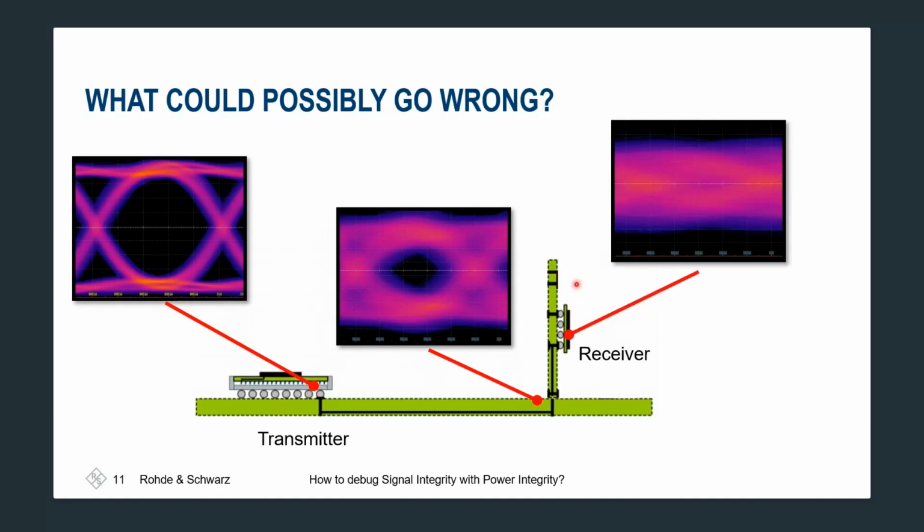Next, the signal is traveling from the receiver board connector to the RX chip input, and for example, in this case, the high-speed serial bus eye will be distorted at this point. Therefore, a so-called equalizer is used in high-speed serial buses, which is able to recover the closed eye, meaning bit errors will be significantly reduced at the receiver side.